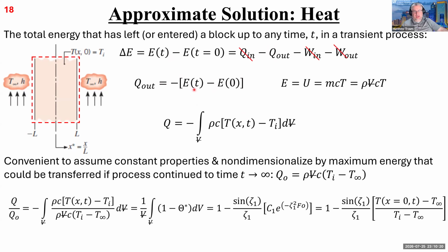And I know that the energy for a closed system, which this is, right? It's just a solid. It's just the internal energy, and the internal energy is just mcT, and mass is just the density times the volume. So here's my expression for energy.